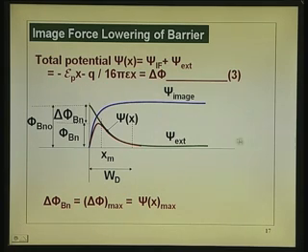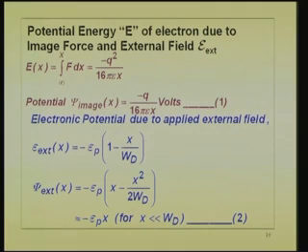Potential is 0 there, I am just putting, if the 0 level is put and shifted down, you will get that. The variation of potential, nothing there, starts falling as 1 by x, goes down. This is due to the image charge. I call it a psi image. Slightly involved concept, but it is not difficult. All that you have to understand is, apart from the usual energy band diagram or the potential, you have one more term that has to be considered, that is that. Now, if you look at this particular diagram here, that is actually the energy band diagram which you usually see. And that can be obtained like this. That is due to the electric field.